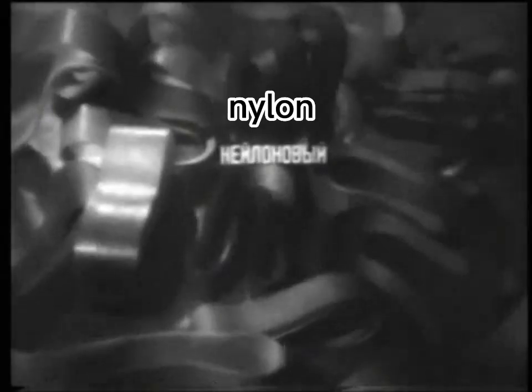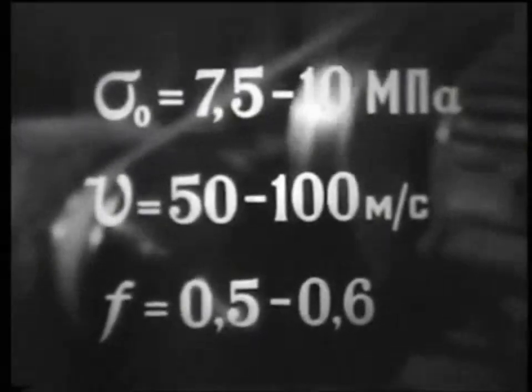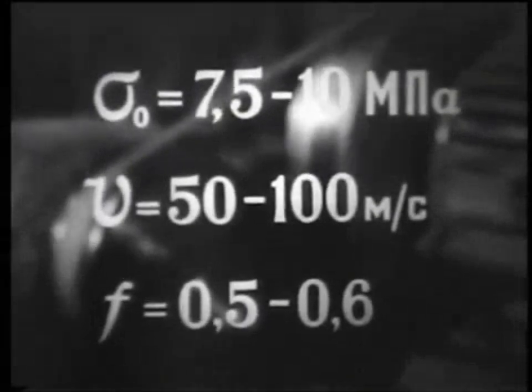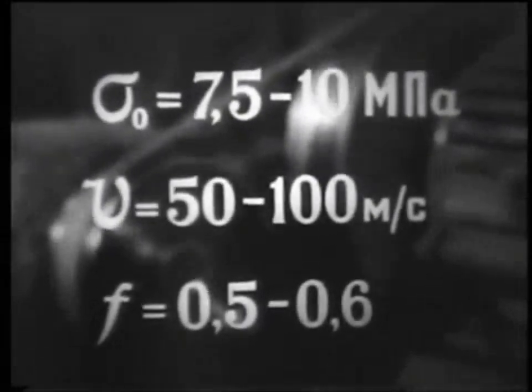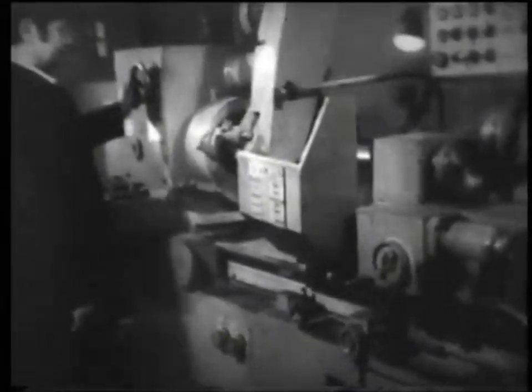The weak link of such belts is stitching. The belt is heavier and stiffer here, shocks and vibrations occur. The introduction of high-strength synthetic materials with friction coating made it possible to create thin, lightweight high-speed belts with a high coefficient of friction and high load capacity. They are used in transmissions with a capacity of up to 1,500 kilowatts.